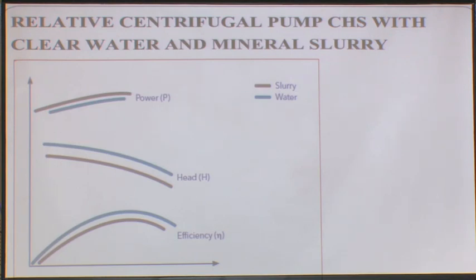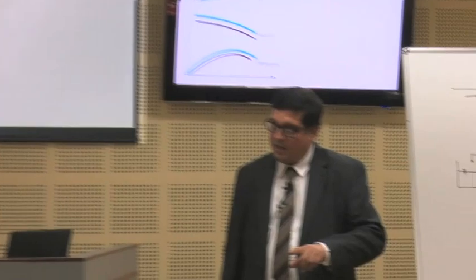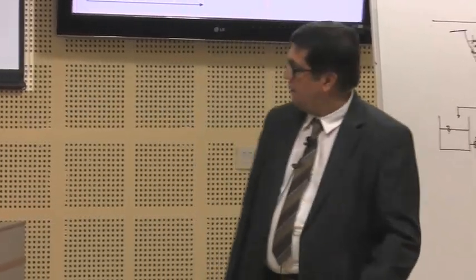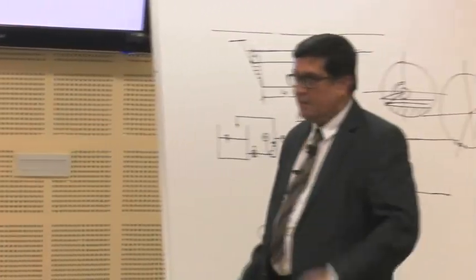So, the question comes, you have to calculate it in terms of slurry, then eventually take it to the water. Then based on your water, he will take where the point will come, against that what are the other features that will be coming there. But do not confuse the slurry head and the water head. These are two different things. You will compute it in the slurry head, transfer it back to the water head, right. This is a big challenge.